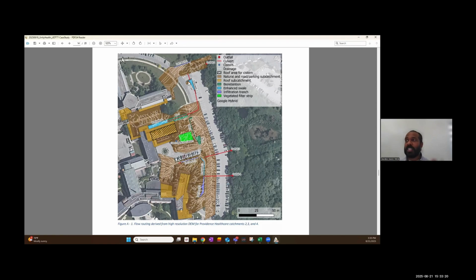We also looked at the detailed site rendering to see where the catch basins were. And we said, what if we didn't change the site too much? We didn't do grading differences and whatnot. Based on where the water is flowing, we're going to put LIDs when we're going to work towards meeting a target, a stormwater quantity and quality target. And then we'll give you a few options of what it's going to cost you, right?